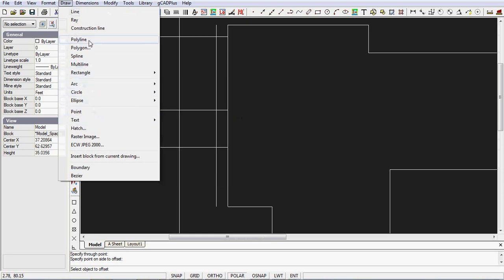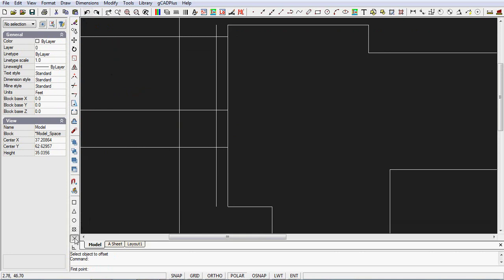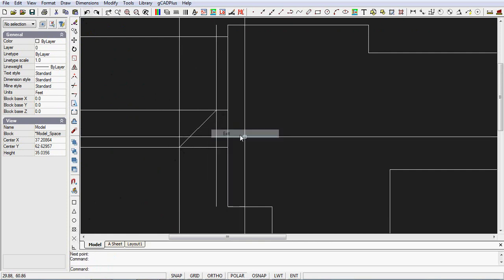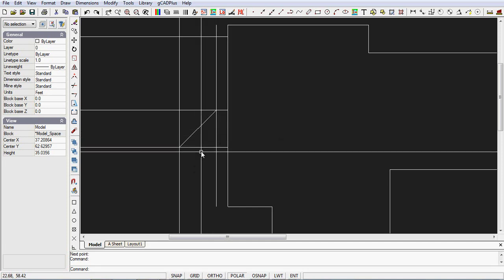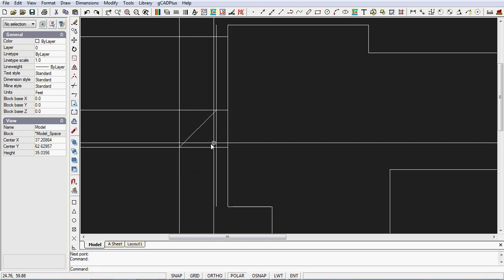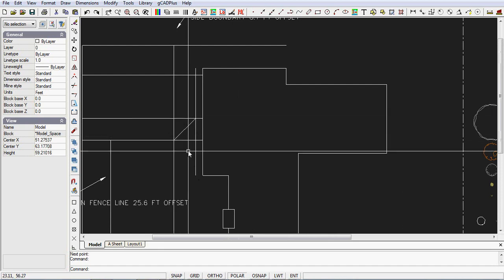You see how we're always making the software work hard for us, not the other way around. We're going to go from this intersection and we snap to it, and we snap to that intersection there, and we can exit. Now we can trim off the unwanted pieces that are hanging through here. So I think you can do that for yourself, but let's do a couple of them.